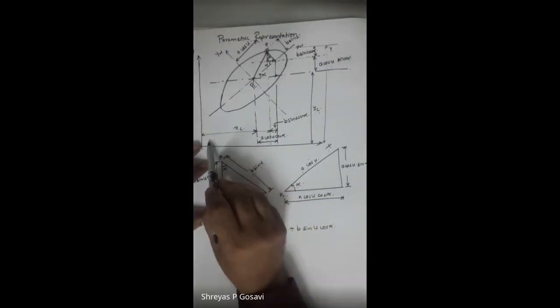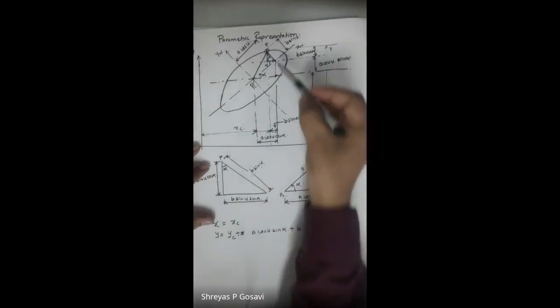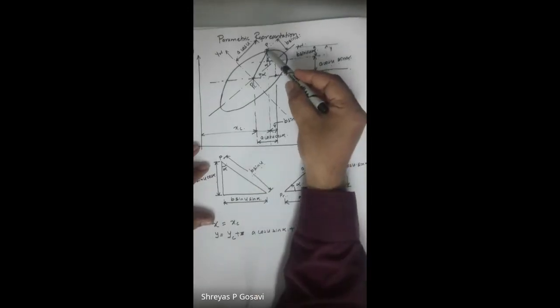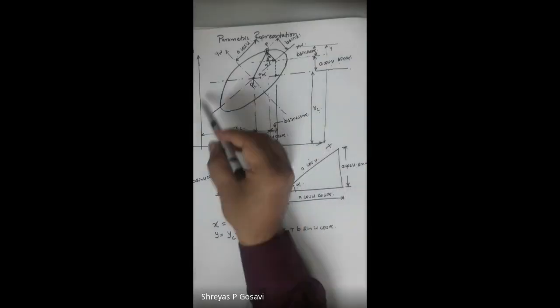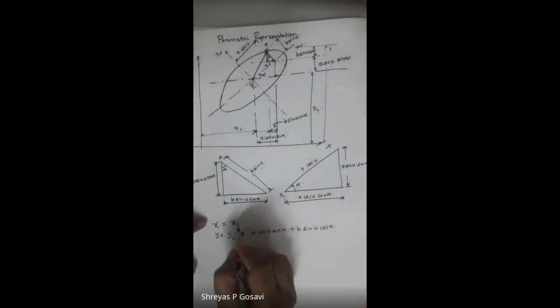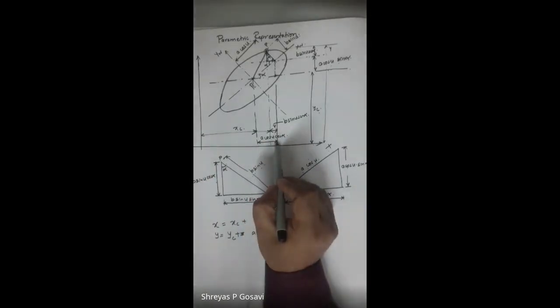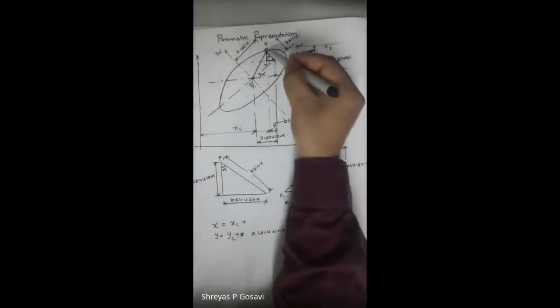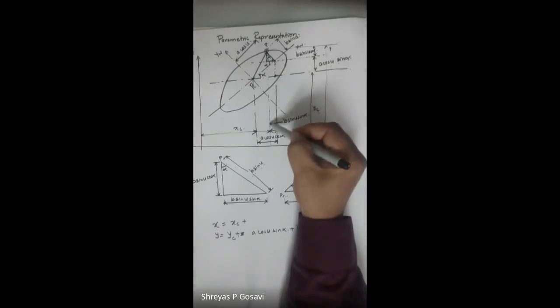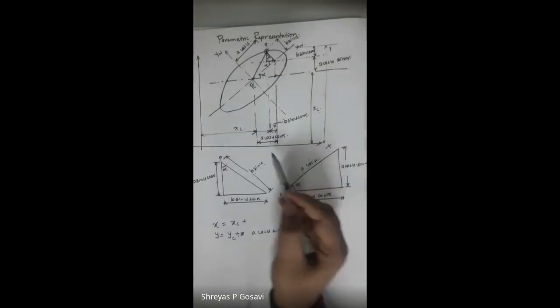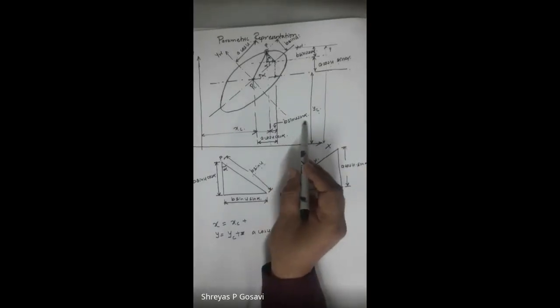We'll simply add up this distance to get the x coordinate of point P with reference to the vertical axis. So this will be xc plus. Now I have this total distance a cos u into cos of alpha, whereas I need the distance up to this line or this projection. So I'll subtract b sine u sine alpha.